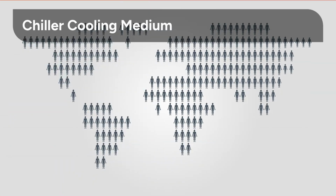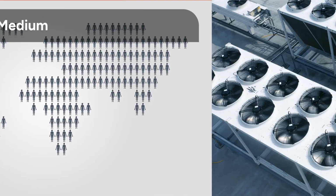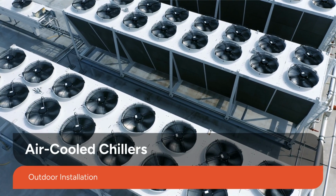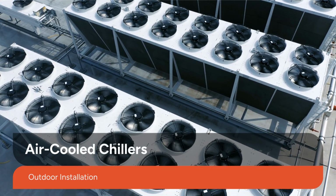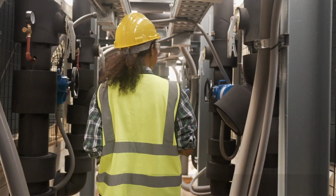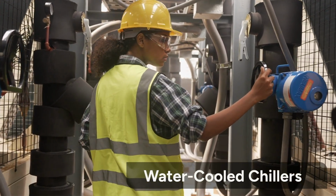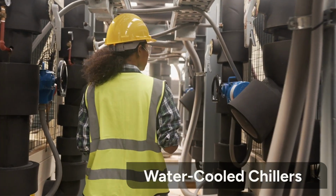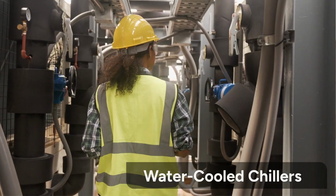Beyond the mechanism, chillers are classified by how they dissipate the heat they remove, which leads us to air-cooled and water-cooled systems. Air-cooled chillers reject heat directly into the ambient air, typically installed outdoors. They are simpler to install as they don't require a separate cooling tower. Water-cooled chillers use a cooling tower to circulate water and reject heat, generally offering better efficiency, especially in large-scale applications, but requiring more system components.